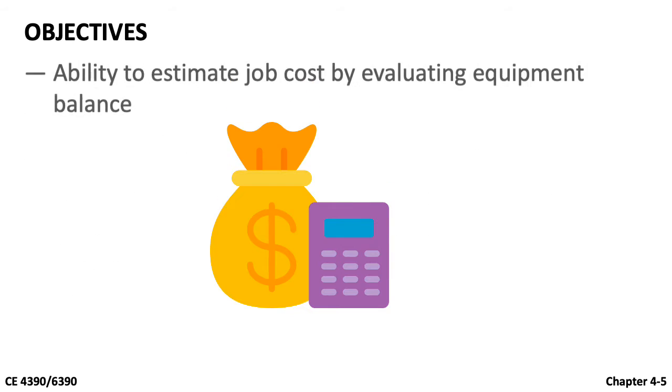And finally, the ability to estimate costs by evaluating equipment balance. You need to know how to calculate how much it costs to use trucks and excavators, so that you can balance the numbers of trucks and excavators and then determine the number of trucks that is most economical.